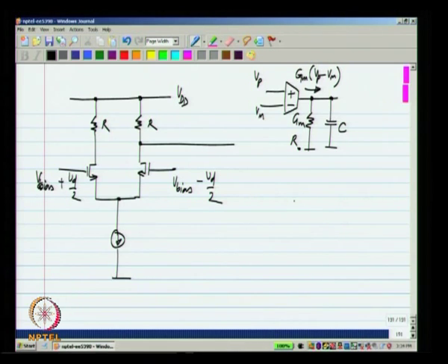Okay. So, let us say I take the output only from this side, and I could pass this through a capacitor. Okay. Now, I also want the output resistance looking in there to be very large. Now, what is that output resistance going to be? Let us assume that the transistors have no output resistance at all, that is they have GDS equal to 0 or RDS equal to infinity. Now, when you have 0 incremental voltage here, the transistors simply become an open circuit, and the resistance looking in here will be just this resistance R. Okay. It can also be thought of in another way.